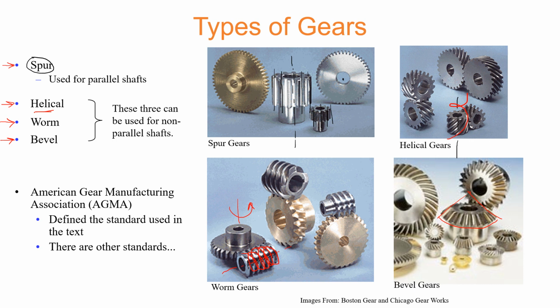So what you're going to do as a little exercise, you are going to study AGMA 6 and AGMA 7 standards, and try to comment on what the difference is between when you say that one set of gears is compliant with AGMA 6 and the other set is compliant with AGMA 7. What is the difference in terms of quality that you have to identify as a little exercise in your notebooks? At this particular stage, we have just presented all the four types that we are going to discuss in much more detail in the subsequent slides.